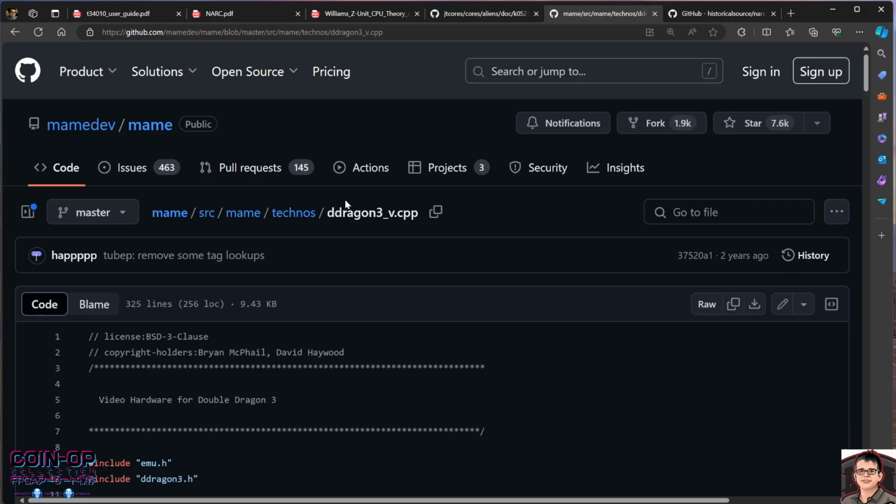So that's MAME. MAME is used for specific algorithms, specific address bus routines, and different sorts of information about the board from a low-level reverse engineering perspective. What are the RAM formats of the graphics? How to decode things? There's lots of reverse engineering information in MAME. It might take us months sometimes to get all that information from scratch if there was no source for it. That's why MAME is a very good documentation source for people who are writing FPGA cores.